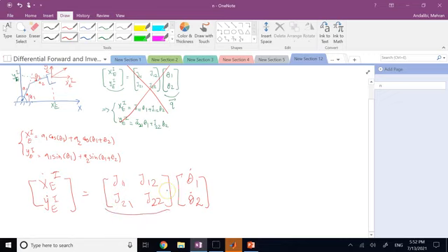It is a very important matrix. It tells us a lot about the manipulator. We'll see, it tells us about singularities. It tells us about how it converts the joint motion into end effector motion, or the forces and torques to each other. And it tells us other stuff we call manipulability. We're going to see that. So this is a fundamental important matrix.